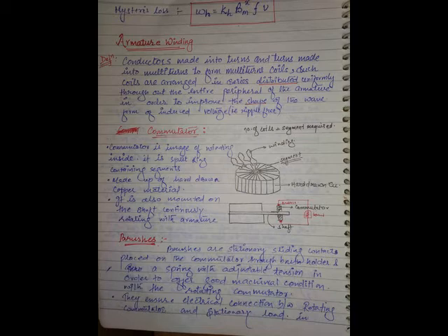All are bunched together, placed in one armature. Instead of doing that, if you distribute these 100 turns, a total of 200 conductors, as 20, 20, 20 on 10 slots, then also you are getting the same voltage.